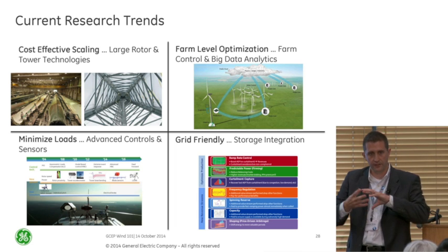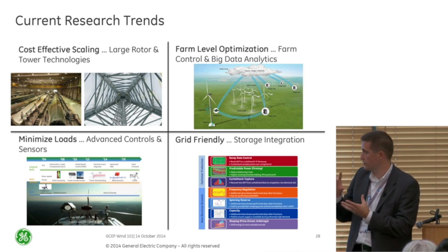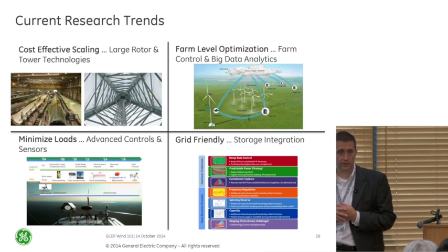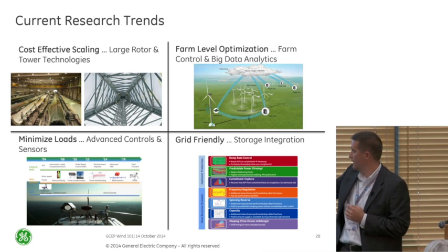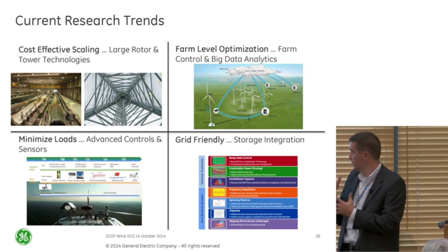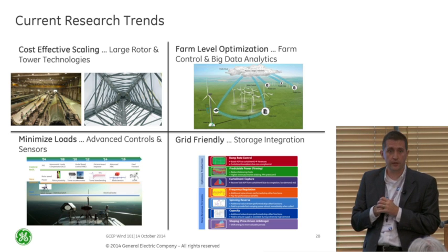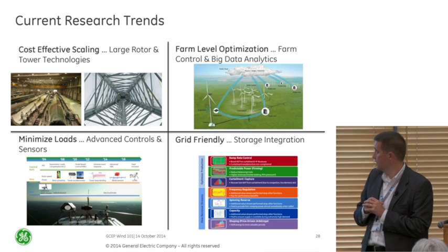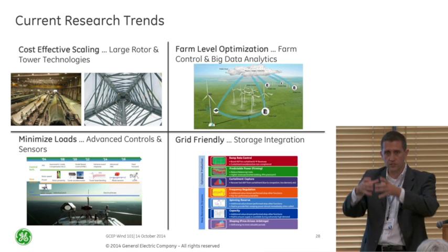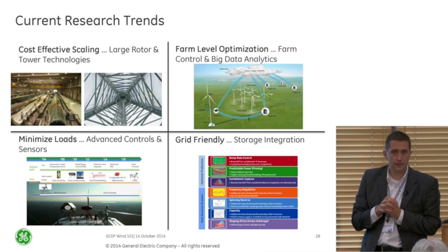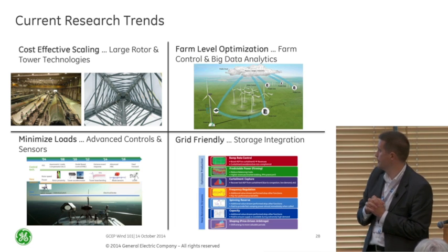A big interface between all three of those disciplines in terms of blade design. And it really translates all the way back to towers too. That's more of a mechanical design. Here's a truss type structure that we have called a lattice tower that we're putting up, a space frame tower that we've done some demonstrations on in California. But basically we have a truss type structure that we wrap instead of having just a straight tubular tower that we think we can shave off a lot of the cost of the tower.